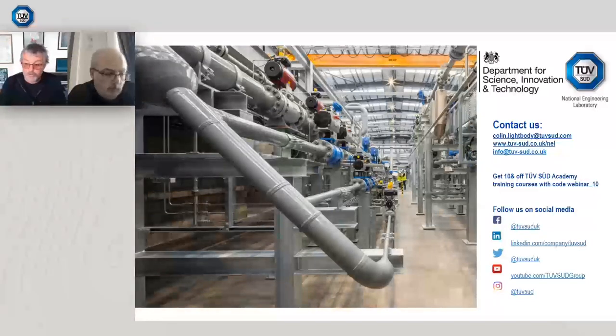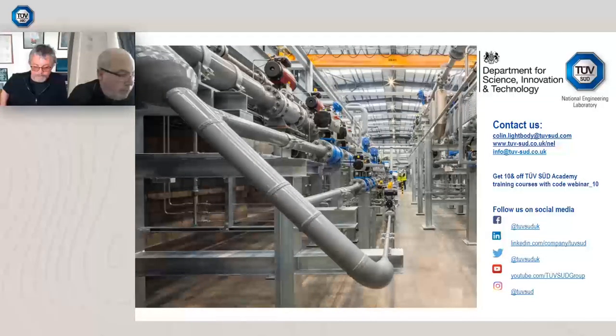The ultrasonic could be used with a densitometer to measure the mass, but yeah, short answer, John, I would say highly variable oil flow, an ultrasonic or a Coriolis meter. You might need more than one, but they generally have higher turn down ratios than turbine meters, PD meters, or differential pressure devices. Good. All right.